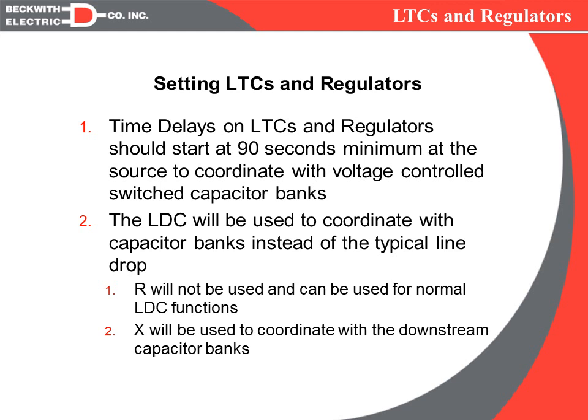So VAR current flowing back through from capacitor banks back to the source is going to create just as much voltage drop across the circuit as it would going from the source to the load. So we need a way to make sure that we don't allow too many capacitor banks to close as the voltage needs to be raised.